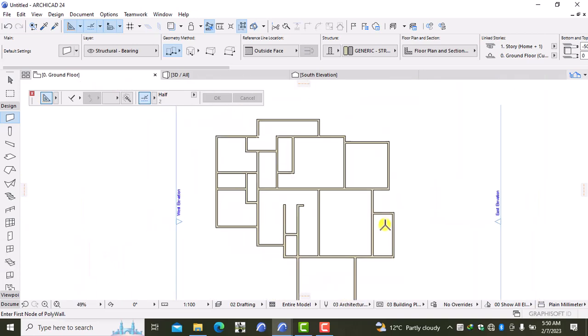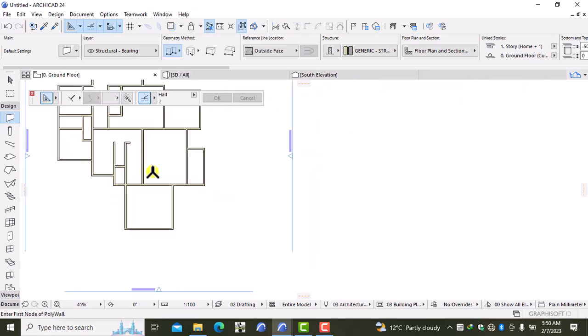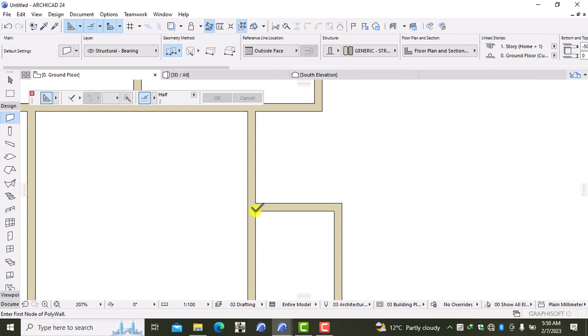Now I can come to this other end and do my chimney over here. So from this point, I'm just going to do a wall and set up the outside face, just use insert face. Just do it at a distance of 350. Enter, and then just drag it at a distance of 1200. Enter, and then do it at a distance of 700, then press enter.